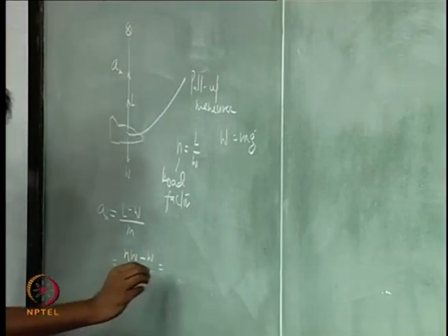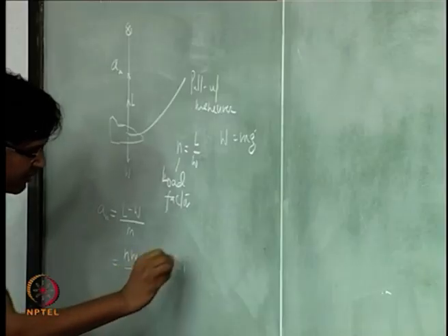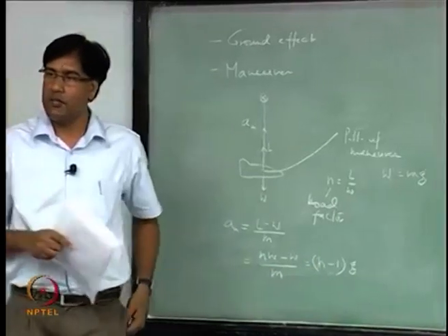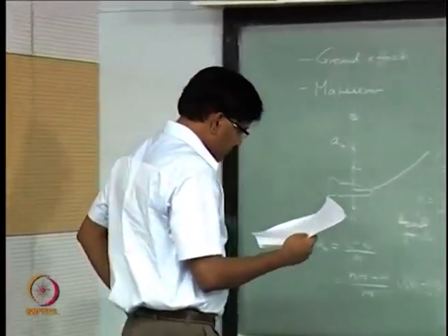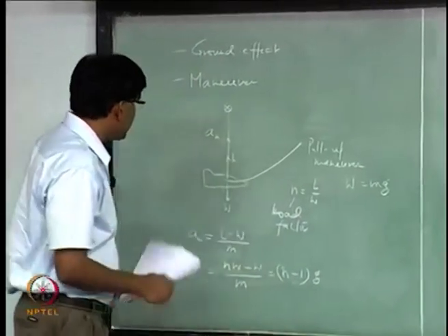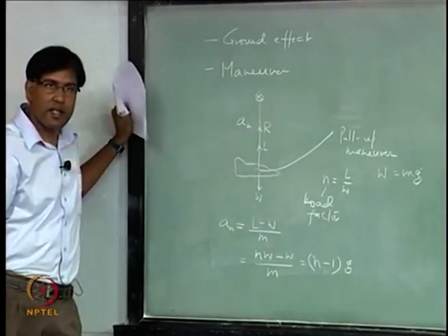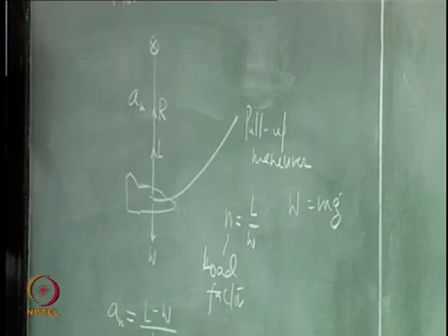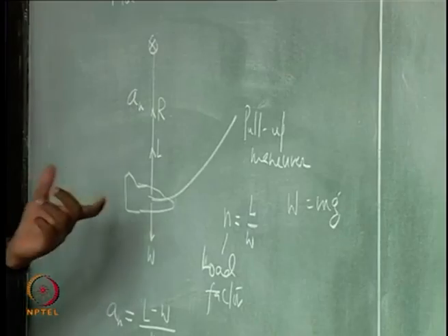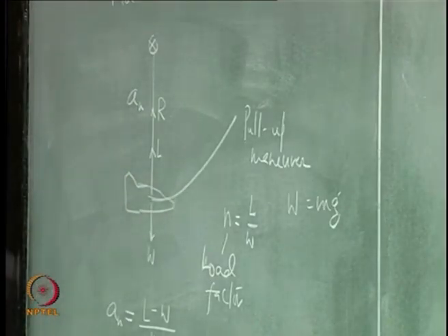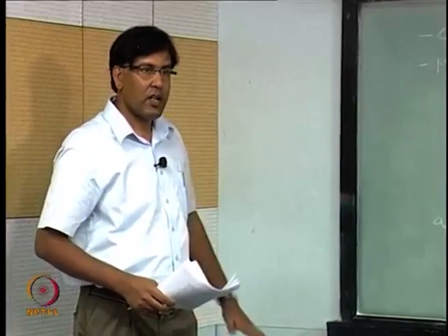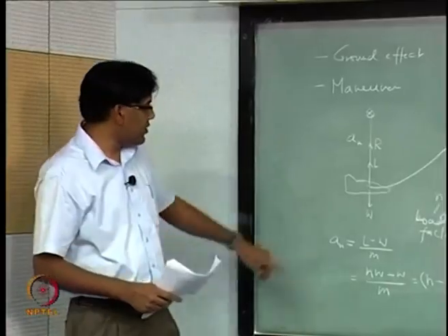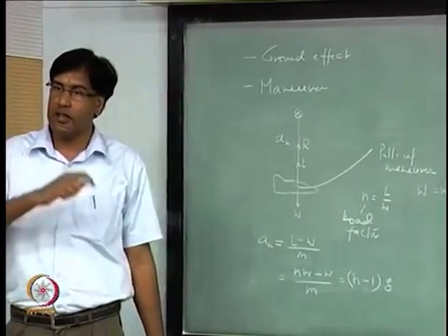So there is a normal acceleration in any maneuver. And also say that this radius is r of this loop, and how is it happening? How are you able to pull up? So you are trying to apply the elevator so that you can create a pitch rate, right, and that is going to take this up, right, and you can do it at constant velocity.